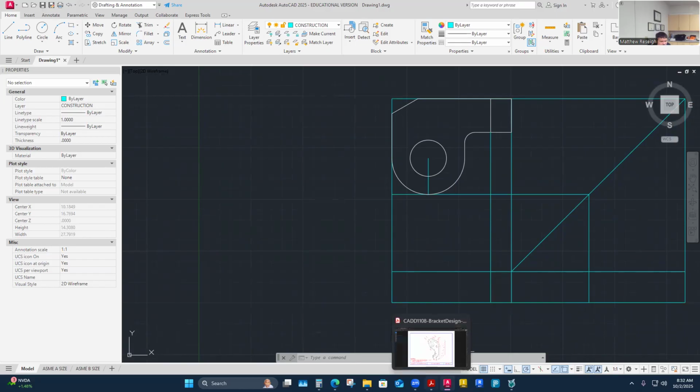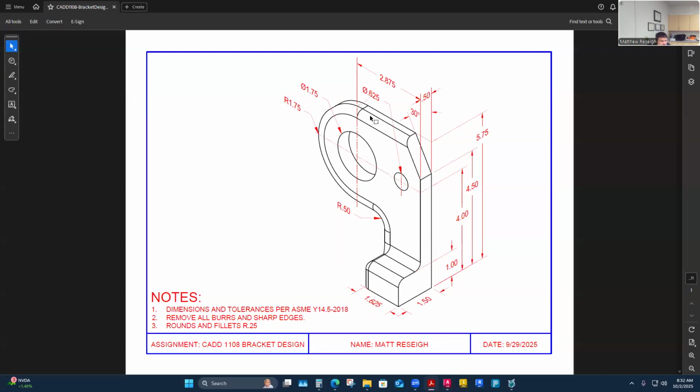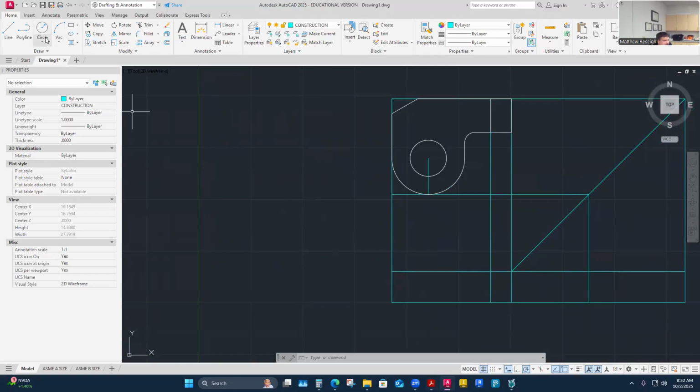So I feel like I might just start drawing that right now. If I look at how thick that is, I haven't pulled out that dimension yet, but this thickness is what I need in my front view, which is half inch. Yeah, 0.5 right here. And I'm really going to trace it pretty much all the way around to that point and then go up. Yeah, okay. So I think it's going to look like this. Maybe I'll start it here where this is the first time I pick up how high that is, but it's like half inch.